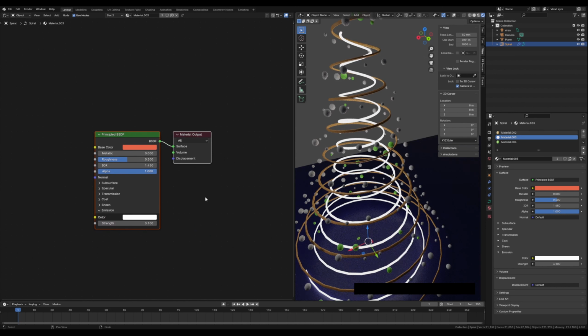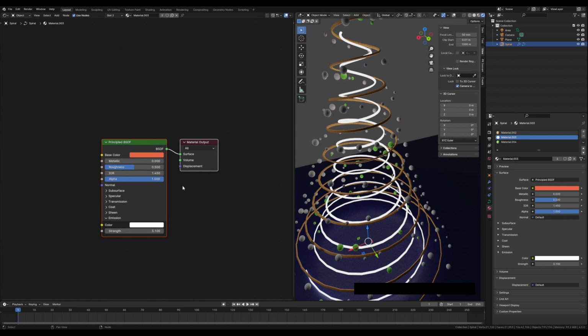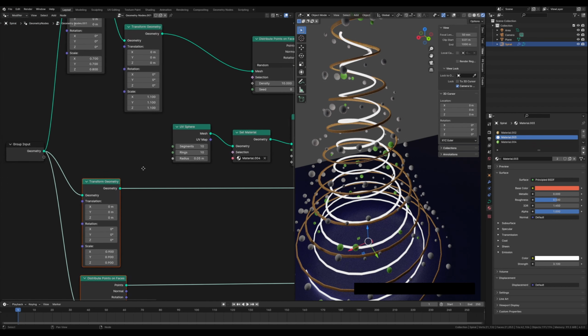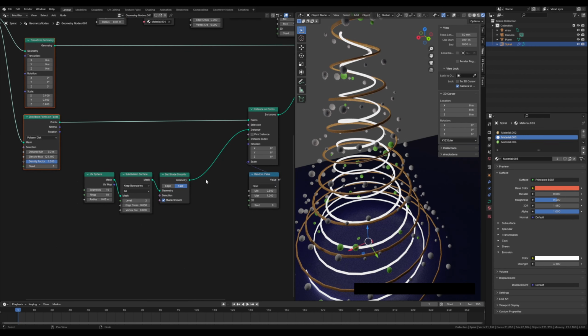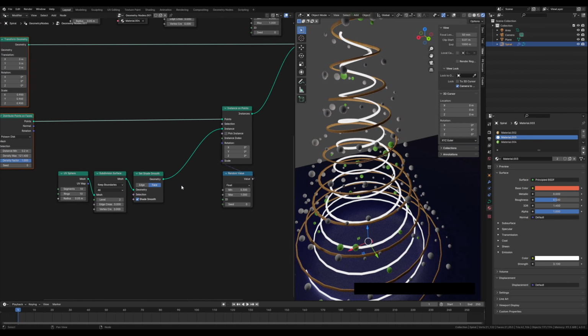Now we want our outside spheres to be a little bit maybe golden, so we can change to geometry nodes, okay. So we can see that we don't have set material, so we have to add Shift A, set material, and place it maybe here, okay.